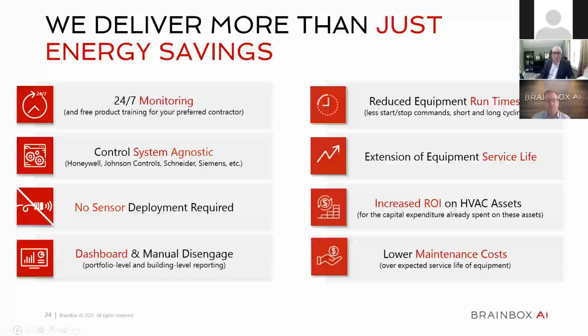As Blake showed, if you can start making smaller changes hours in advance, as opposed to waiting until you hit your cooling or heating temperature set points, you're going to be operating your equipment a lot less often and a lot less harshly. So you're going to see savings in the extended life of your HVAC equipment, as well as lower maintenance cost. Next slide, please.